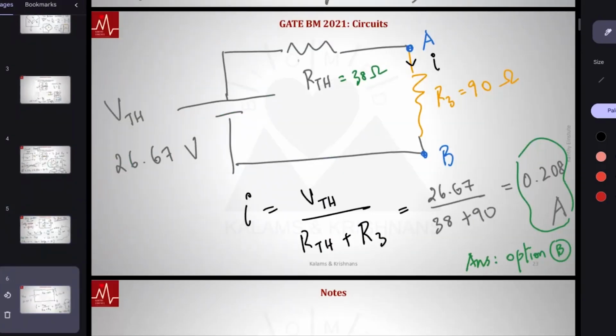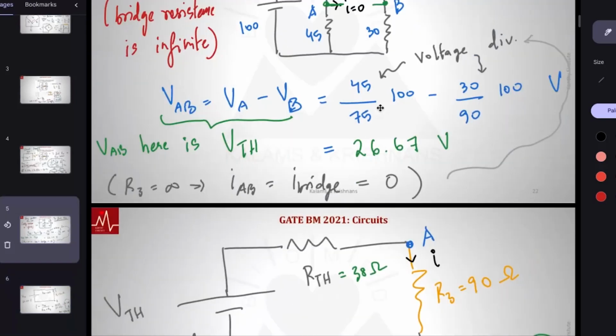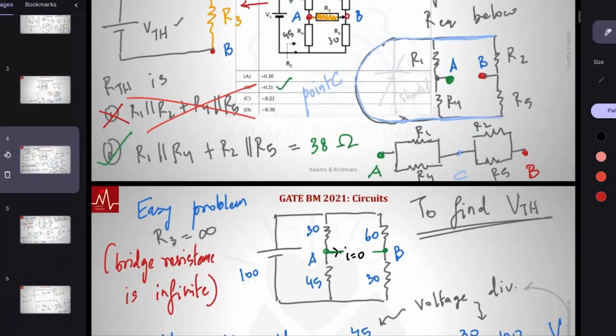Be careful. Students make a mistake while finding R Thevenin because they typically write option 1. You have to see where the equipotential points are. Connected equipotential points will behave as one point. All the blue thing behaves as one point. Those are wires. Isn't there a negligible potential drop in the wires? Compared to this, the changes are happening in the 6th or 7th decimal place. That is the difference. When is it negligible? It would be a fair question, sir.